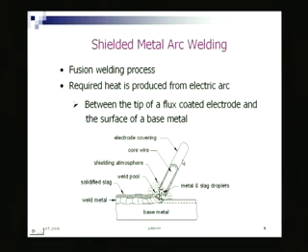So here what you see is that this is our electrode. Here we have the covering, the coating over the electrode. The central part is the core wire which carries the current and acts as the filler metal too, right. Here you have the so-called welding arc, the electric arc, where schematically we have tried to show that metal transfer is taking place.